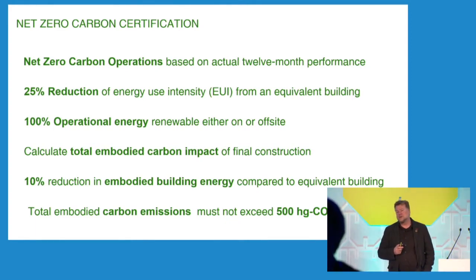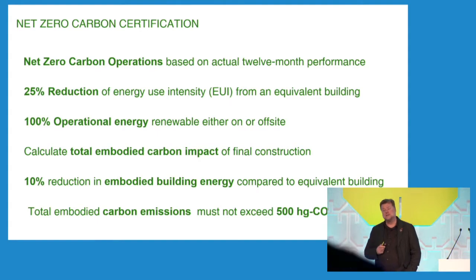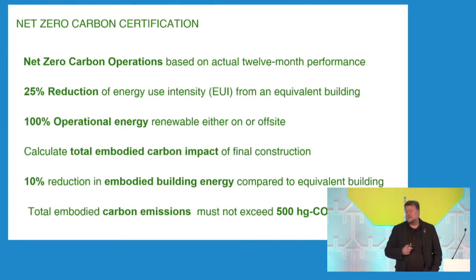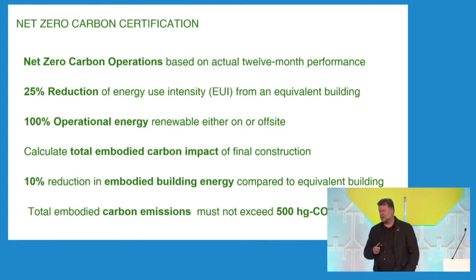And it requires also a 25% reduction of energy use. So that's the energy use, the intensity of energy of the building, which for a laboratory building is actually quite a challenge because they are very energy intensive. And it requires also 100% renewable energy, but it doesn't have to be generated on-site, it can be generated off-site, which is what we're doing as a mixture at Arizona. And then you have to calculate the total embodied energy of the building and have a reduction in the comparative building, but also there's a maximum embodied energy per square meter. So there's a series of different challenges you have to get over.